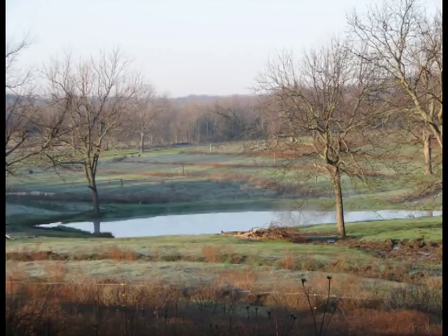Goes all the way out here, hits a pond, fills up, and comes back here, and comes out 15 feet below this particular pond here. What used to go a half a mile and it's off the property, now went a half a mile that way and a half a mile back, and it only moved 15 feet down that valley. That's keeping your water on the site.